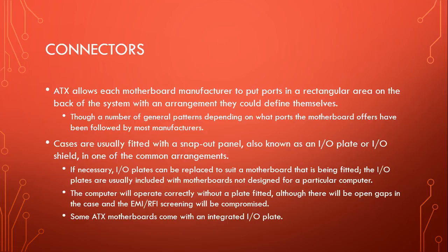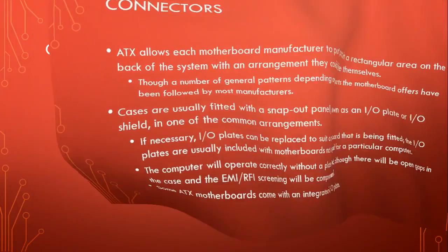Now, believe it or not, the computer will operate correctly without an I/O plate fitted. It's not going to stop functioning if your I/O plate's missing. Although there will be some open gaps in the case, because you're missing a whole piece of aluminum, and the EMI/RFI screening will be compromised because now you have this open area for electromagnetic frequency to come through. Now, some ATX boards also come with an integrated I/O plate, which means that rather than it being another piece of metal that you attach, it's integrated right into the board, so you cannot remove it.